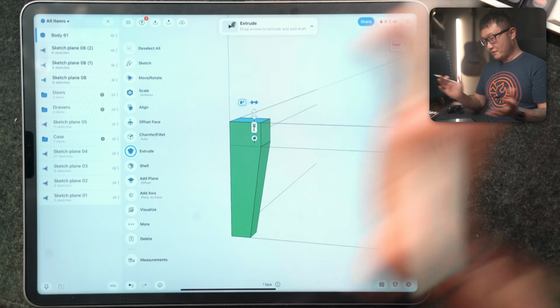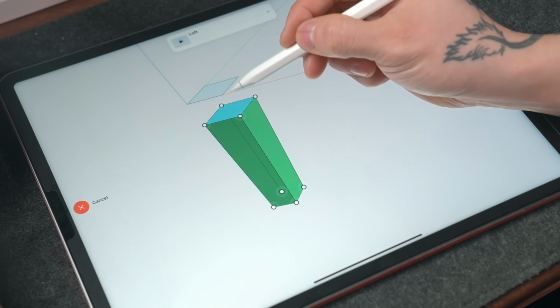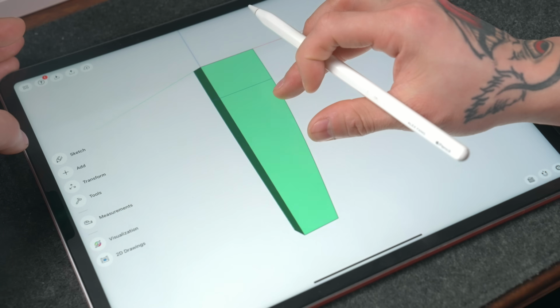And there's our leg. Okay, so just so you guys know, loft is usually used for creating smooth transitions between surfaces. So if we went in here and picked all 3 surfaces in one loft operation, it's actually gonna create this curved body on this bottom half. Now, there are other ways to create this shape that we wanted, but I think the method I showed you is probably gonna be the quickest.